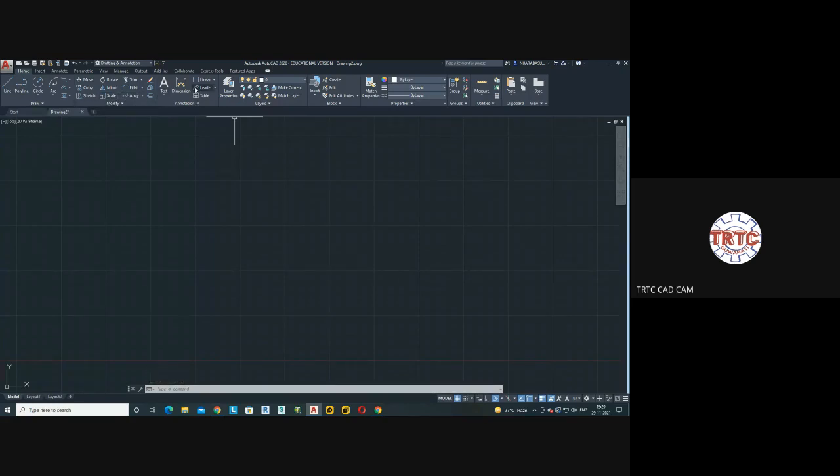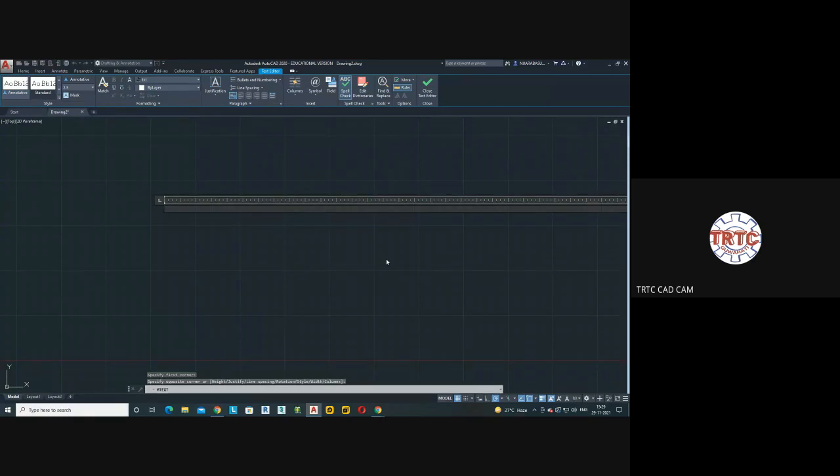Okay. Annotation. I showed you this annotation. You want to draw any text, you can go for text. Click here, make a box. Write anything. You can press the escape key, or else if you want to modify this, you want to change the font, you want to resize the font, you can do it there.